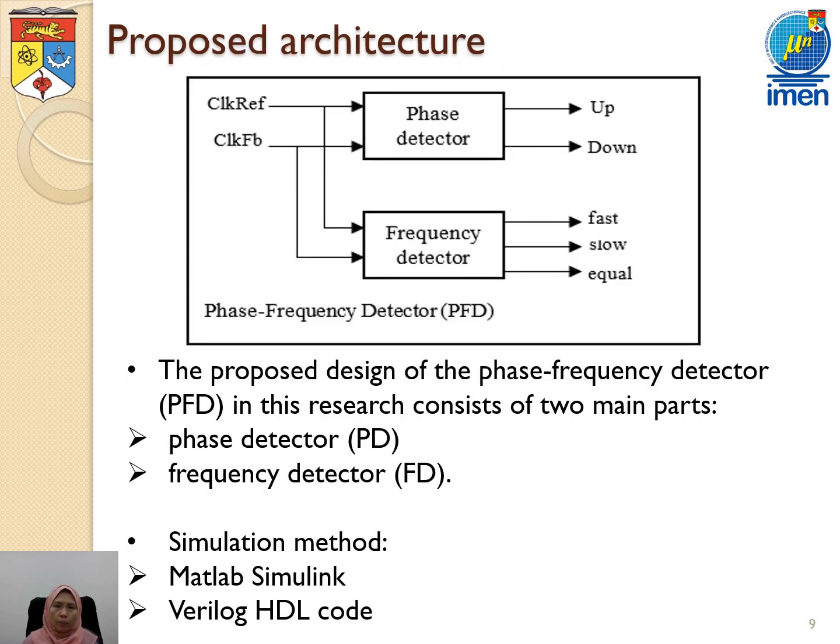So this is our proposed architecture for the phase frequency detector. It consists of a phase detector and frequency detector, involving two input signals, clock reference and clock feedback. The phase detector output is up and down, and the frequency detector output is fast, slow and equal.